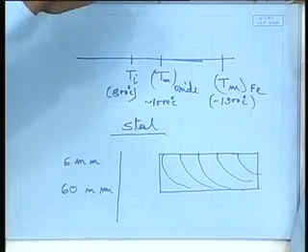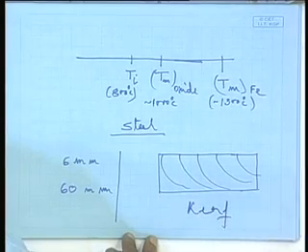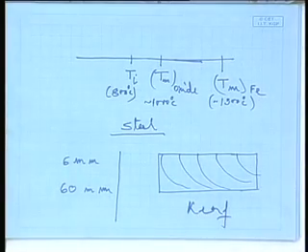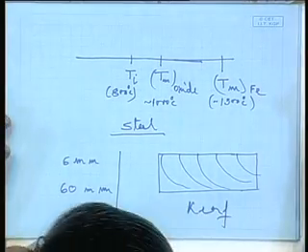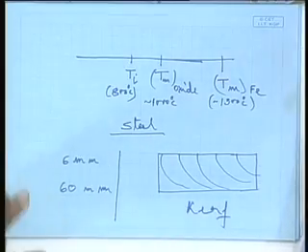So, in the process at one location you have to keep the torch for a longer period, or in other words the speed of movement should be slow. Once the speed of movement is slow, it is moving this way, so it will form like this, and those are called curves. This cut edge is called a curve, and it will not be a very smooth curve, right. As the thickness increases, the cut edge will not be good. So, what is the solution to that?